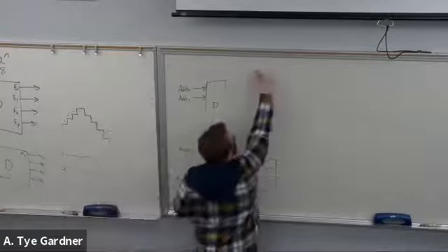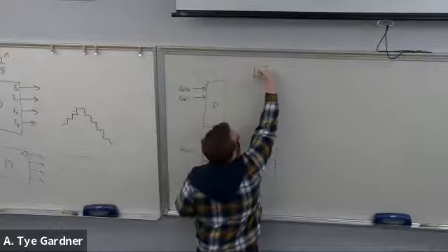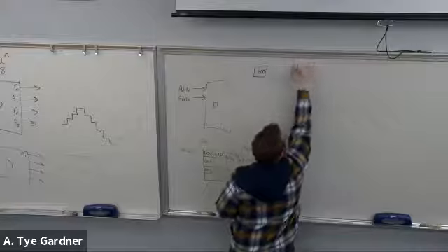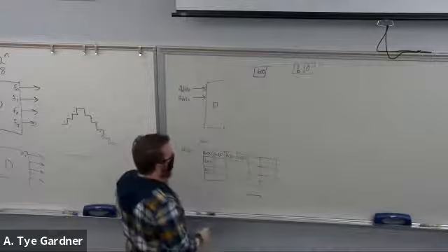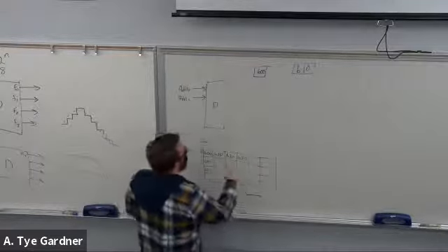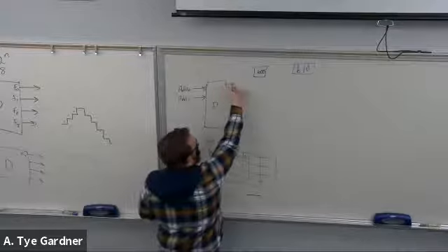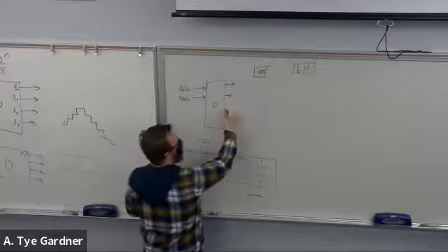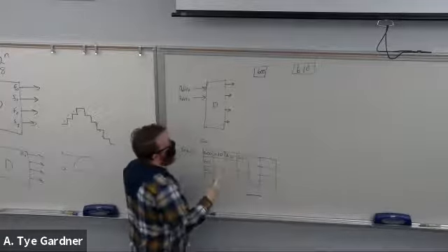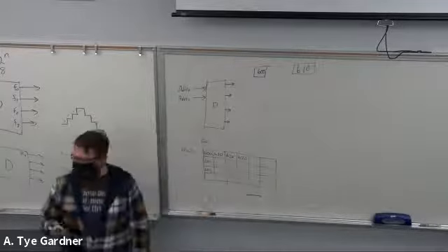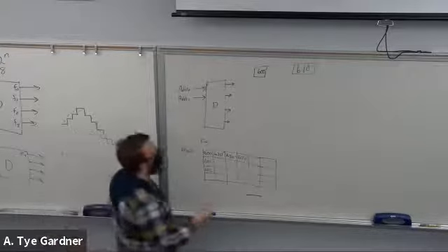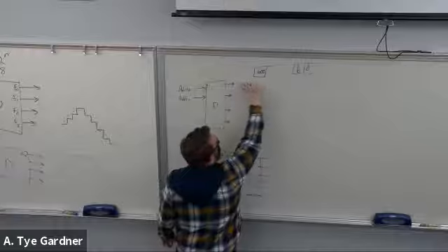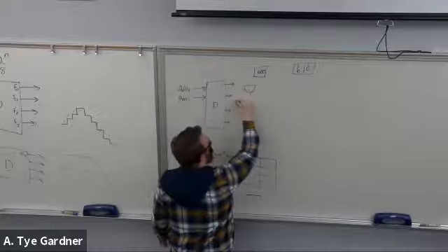So let's take bit 00 and bit 10 and say that I want to access those at some output. Well, this, I already said, is giving me 1 hot outputs. Well, I know that one and only one of those outputs is ever going to be true. So what I can do is set up a couple AND gates.